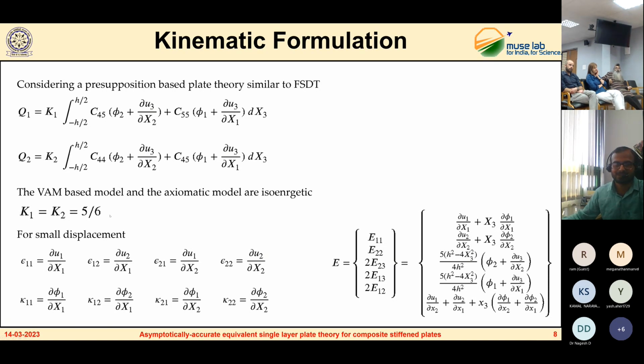So I think these aspects need to be highlighted whenever you present, because some of these very important findings could tend to get overlooked. Once you have this particular model in place, you could look at various other Timoshenko applications where these shear correction factors were empirically assumed. Now you will probably be able to get, for at least certain regular geometric shapes, the actual asymptotically correct values of these so-called shear correction factors, which of course, if we use your theory, we won't even need. Yes, sir.